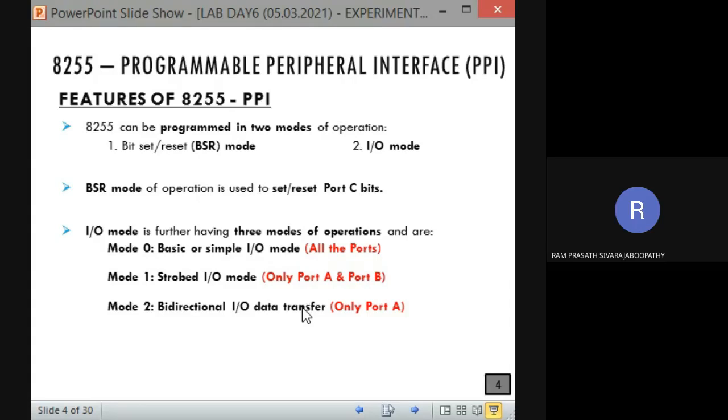What do you mean by interrupt driven data transfer? If I want to read data, the processor won't initiate the communication. First, the input device will tell 8255 that it has data. In turn, 8255 will interrupt the processor to read the data.